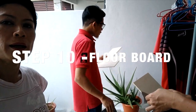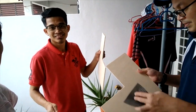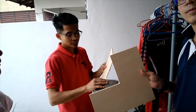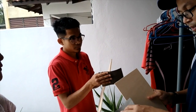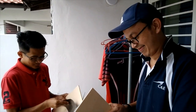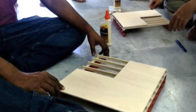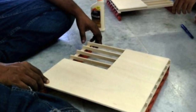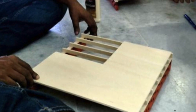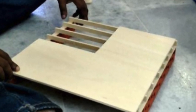Floorboard is also known as a subfloor layer. It is constructed prior to floor finishes. It provides cover to the floor joist. Traditionally, in suspended timber ground floor construction, a soft wood board is used. The thickness should be at least 20 millimeter and the material must be from a durable species or treated with a suitable preservative. On the working model, we are using plywood. To enhance the visibility of the floor joist, we cut the plywood into L shape.